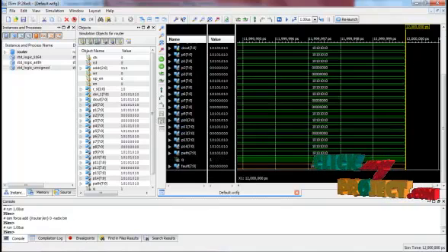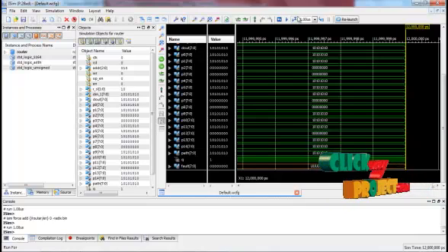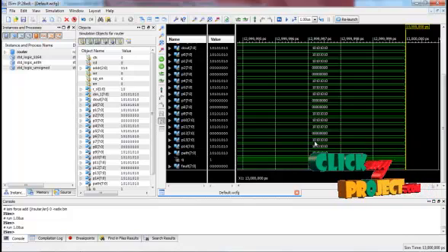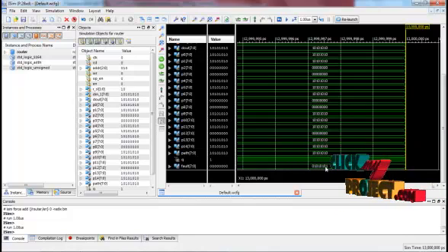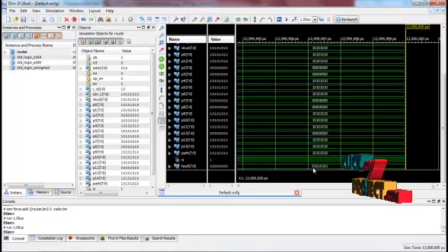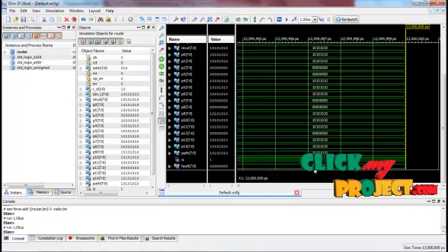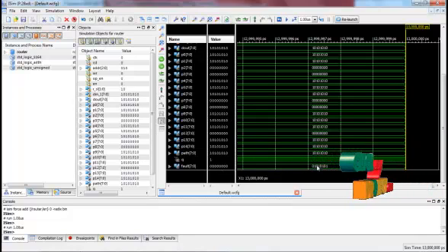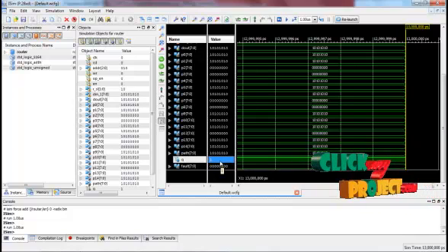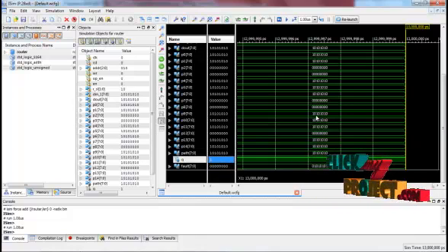Now the data is undefined, that is the fault node has entered into the process and it will change. Our input is 101010, then the fault node is identified, which changes the input to the complement form. So we have to identify this, and the checking process is done in this place. So data in is not equal to 0, 1, that is the fault node. So we have to produce the output as 1, which is nothing but our process contains an error, that is a fault node. We have to identify that fault node.